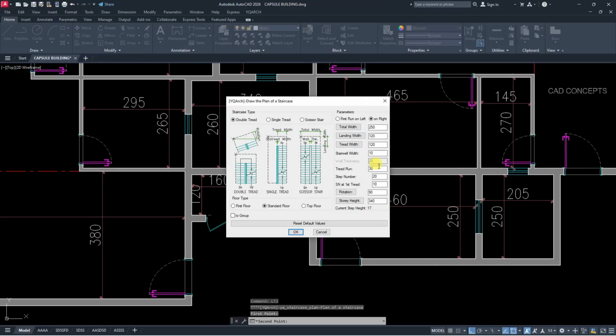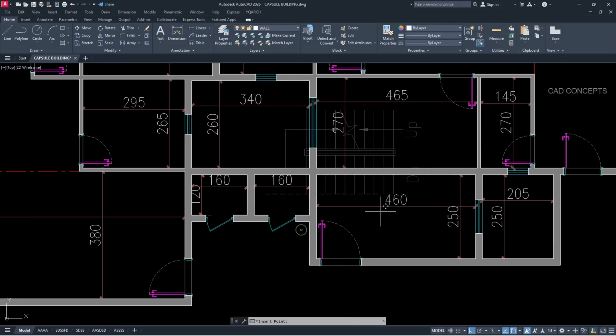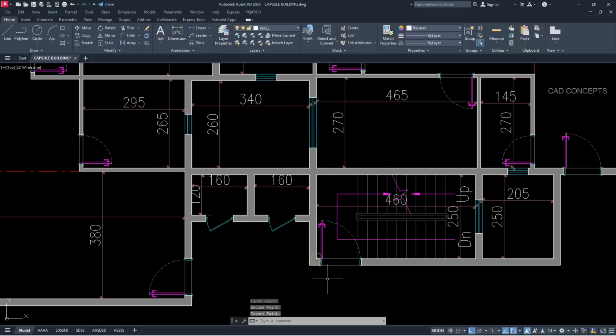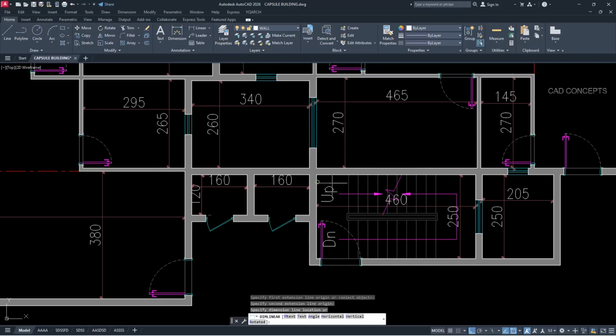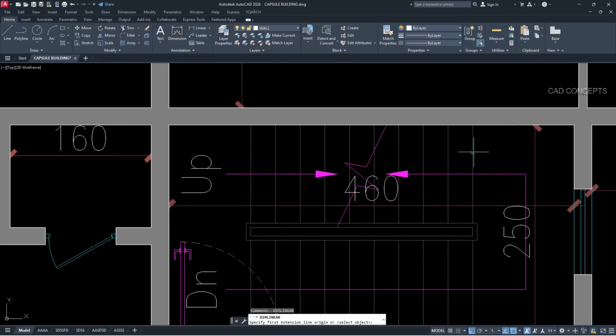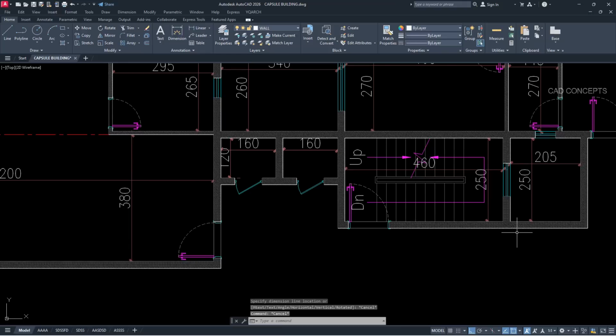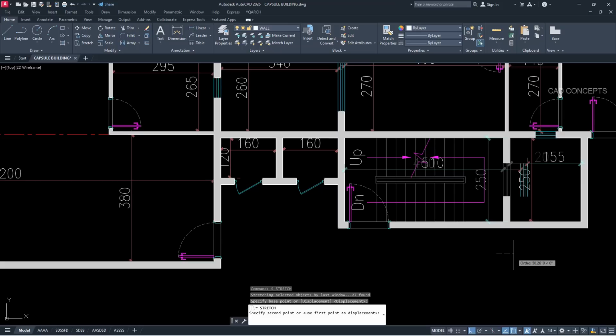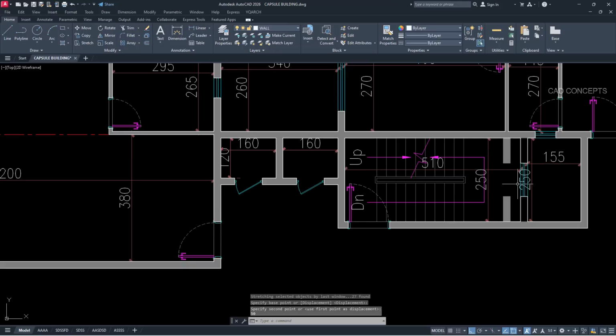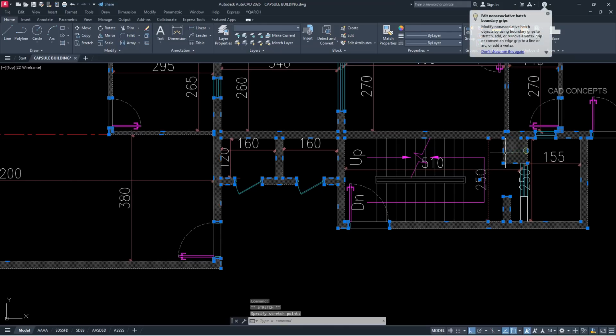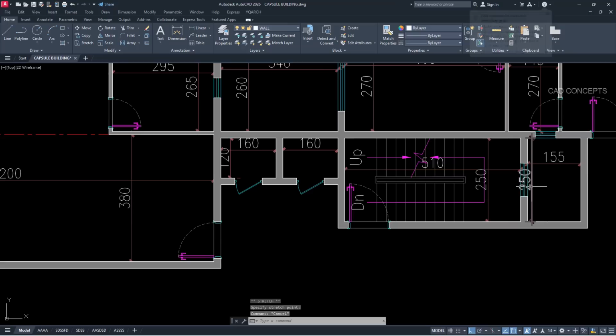Choose your stairwell width 120, tread 28 centimeter. Okay, and just simply place here and mirror another side. So 115, 93, much smaller. We must need 120, both side. Okay, let this stretch 50 centimeter. Okay, we have stretched our duct area to match our staircase required spacing.